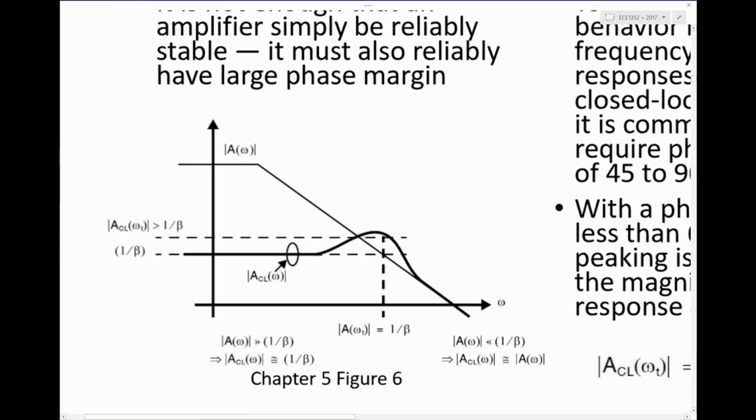It's not hard to imagine that you just may not want that kind of closed loop response. You just don't want to see that peaking. You don't expect, if you're designing an amplifier, to have a gain of 10, and then all of a sudden at some high frequency, the gain goes up to 15. That's maybe really undesired and may cause big problems.